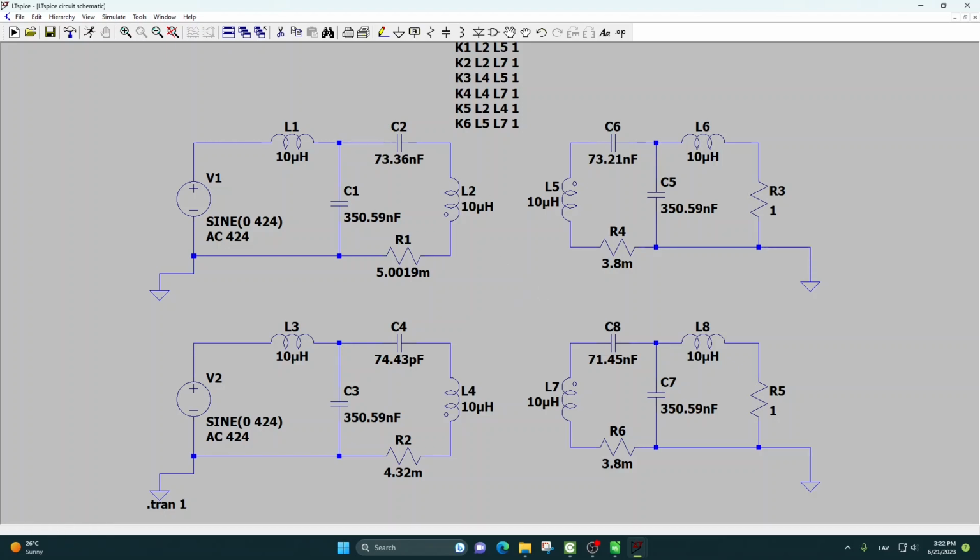You can of course skip this step, in which case, if you have not defined self-inductance for your coils, CENOS will simply predefine some default values and use those as the starting values. But then of course the convergence will be potentially slower and the calculation time could also be larger.